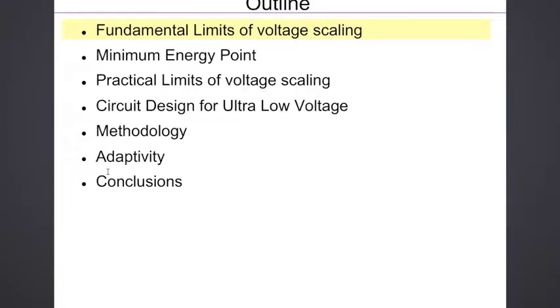Question: how low a voltage can I use? And what is the lowest voltage I can use? Now, in some of the textbooks, you see the minimum voltage that you can use specified as the sum of the thresholds of the NMOS and PMOS and so on. That is really not the case.